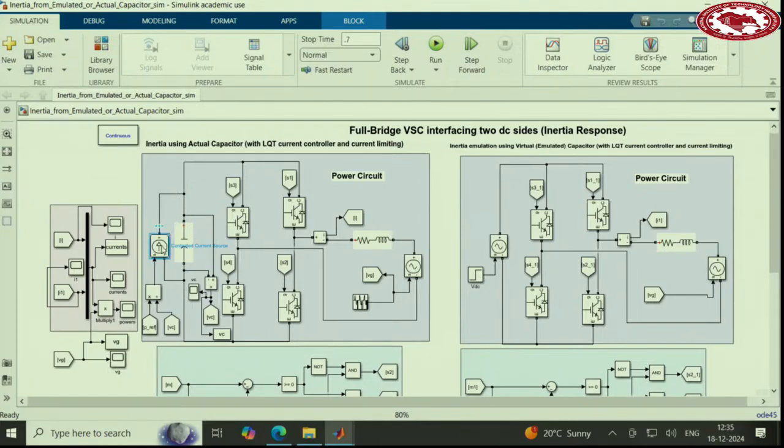So choose that current equal to the power divided by VC. The amount of power, P reference or P set point, divided by VC, is the current, and you apply it to this controllable current source, and that means that this amount of power, P ref, will be coming from here.